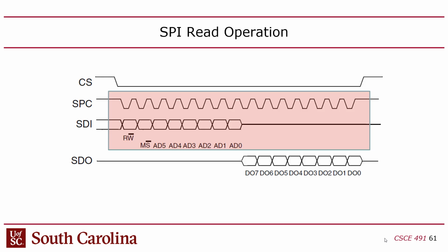Well, they're dicks, basically, because everyone knows it's MOSI and MISO, right? But like I said, because it's not governed by the IEEE, you're allowed to change the names, and that's exactly what they do. So now we have chip select, but just keep in mind, map in your brain that it's slave select. So that goes down, and then you have this, MOSI and MISO.